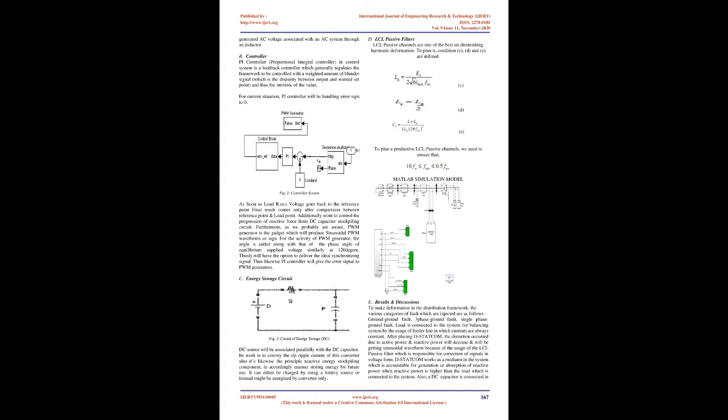I out equals IL minus (VTH/ZTH) A, I out equals IL minus VTH/ZTH B plus VTH/ZTH B. Considering equation B, the output current will address the voltage sags by changing the voltage drops over the system impedance, equal to R plus JX. We can mention that the effectiveness of the D-STATCOM in correcting voltage sags depends on the value of impedance, equal to R plus JX, and the fault level of the load bus.